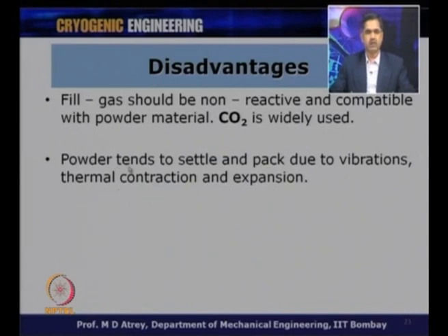So, although we say we have minimum vibration, there is some vibration, and over a period of time this powder will tend to settle, thereby exposing a particular path for heat inlets. Or we can have cake formation at the bottom where the powder settles, and this is one of the very important disadvantages that has to be considered for a particular application.